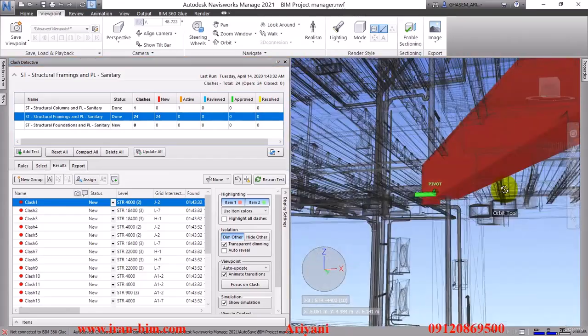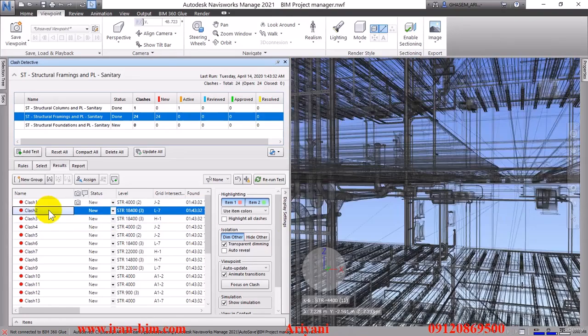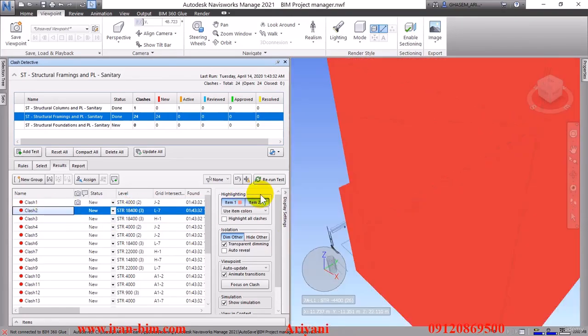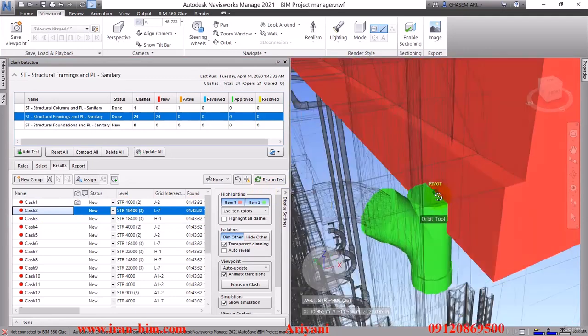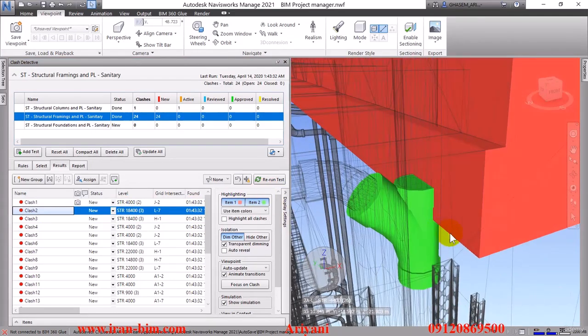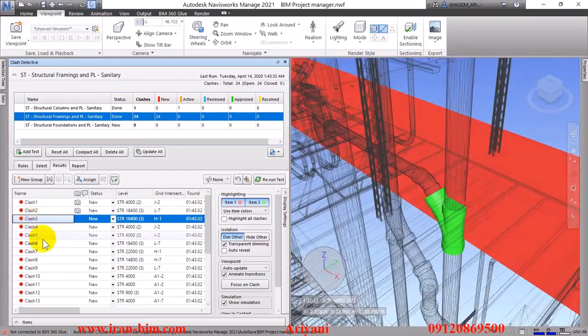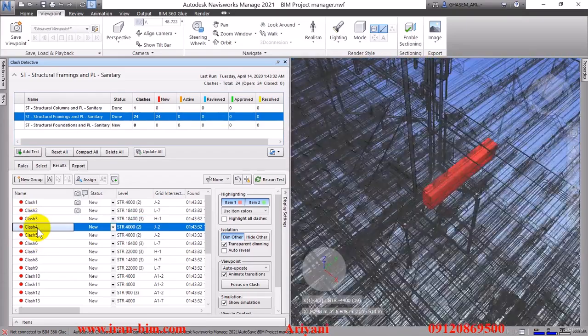So now we have 24 clashes in here. And these aren't actually major clashes that could cause problems. For example, here, if we move the vent pipe a bit, the problem will be fixed. But they are clashes either way. For example, this one, we will have to adjust this and put some gap between these two and bring this outward. But doing that may cause a clash with another item, so we need to be careful. We'll have to be sure to check all of these.